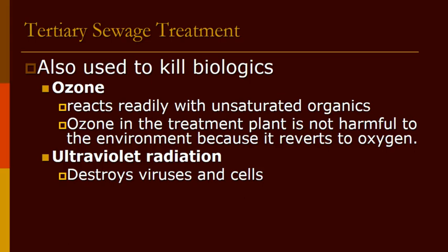Ozone. You can bubble ozone through the water. It'll revert back to oxygen. It really destroys cell membranes, which is a great thing, and it can cause all kinds of damage to cells. So it's good in terms of it's not going to be the environmental problem, and you don't have to remove it. It also means that you need to redo your treatment plant. So if it's an older treatment plant, then you'd have to refit it. Otherwise, you'd have to build it so you are making and bubbling the ozone through.